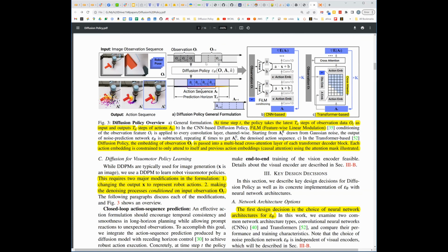So it really is stacking multiple observations of history and packing them in there, and it's making multiple action predictions all in one fell swoop, in one inference call, one prediction call. Right. So the little a's are the individual actions, and the capital A is the action sequence. So it's outputting one entire sequence each time you run inference just once. Yeah, and so that's basically what you were saying, that it can be smarter.